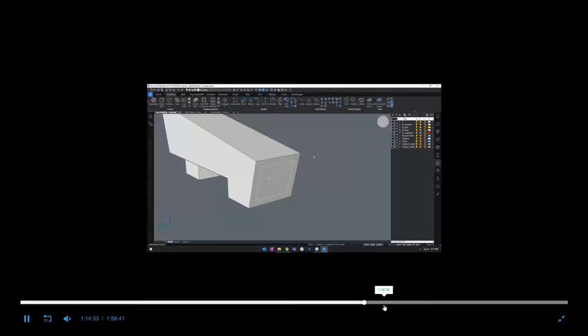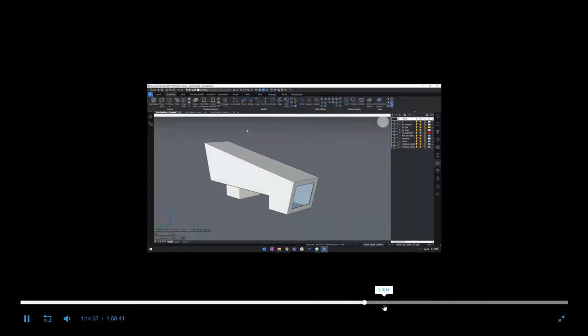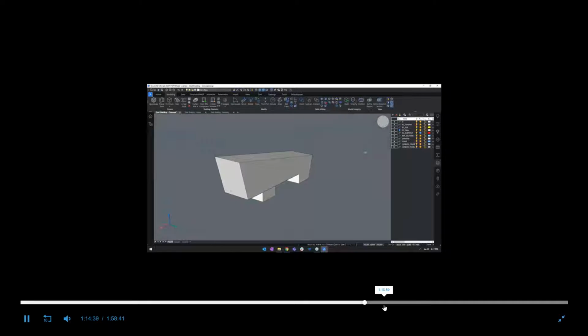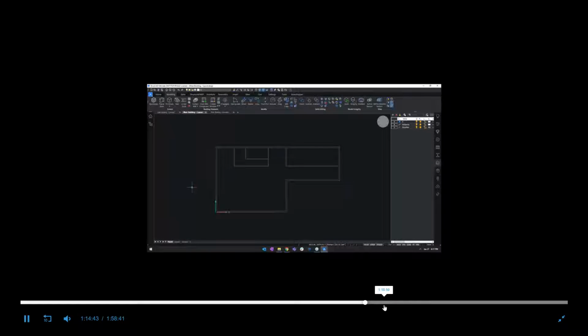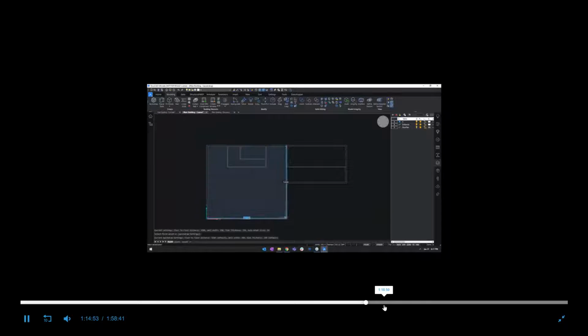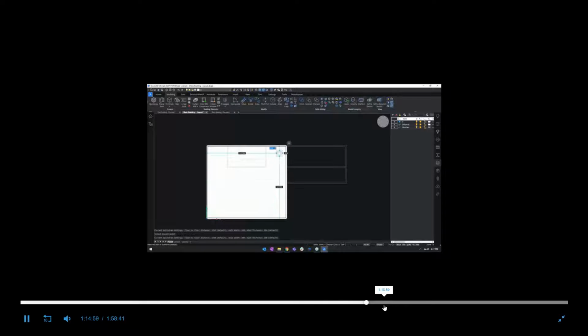It's also possible to create a layout for a building in 3D starting from a 2D layout. So in this case, we have some 2D geometry. And I can use a quick draw tool to easily create walls and slabs based on this 2D geometry. Sorry if there is some delay here. It seems like GoToWebinar and Quick Draw don't play together nicely on my machine.